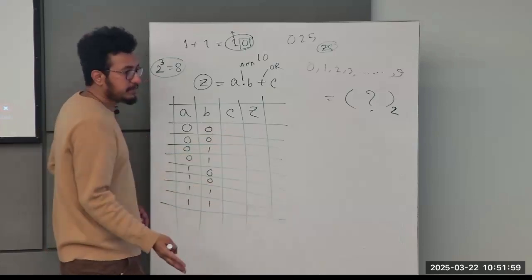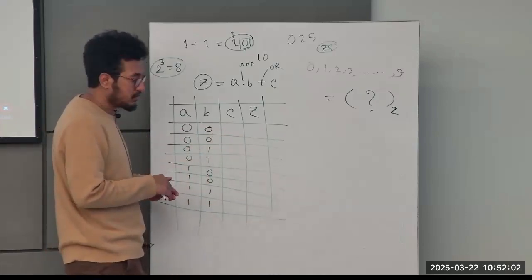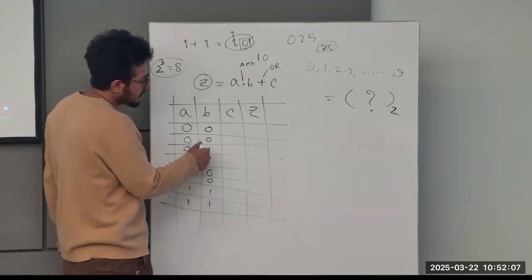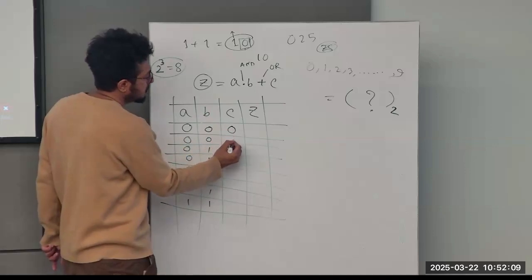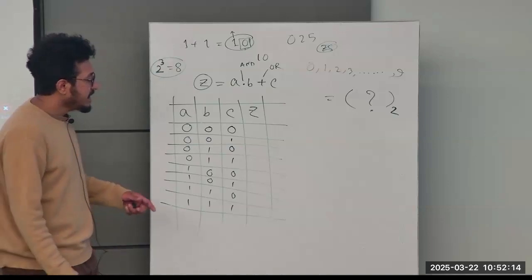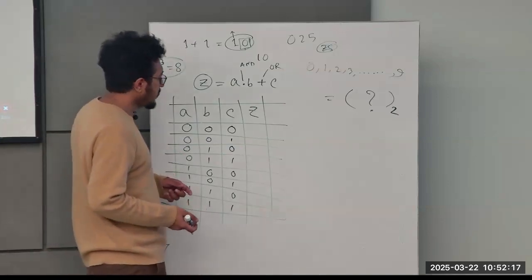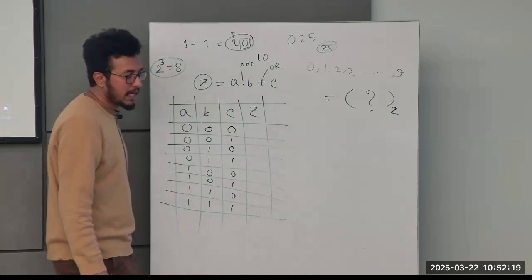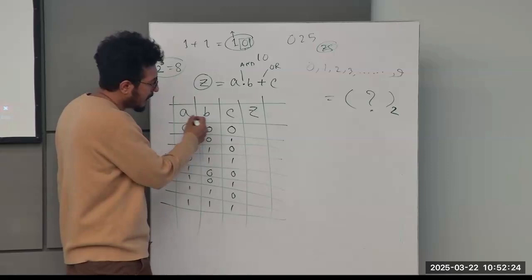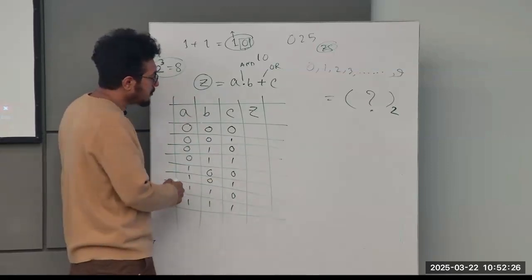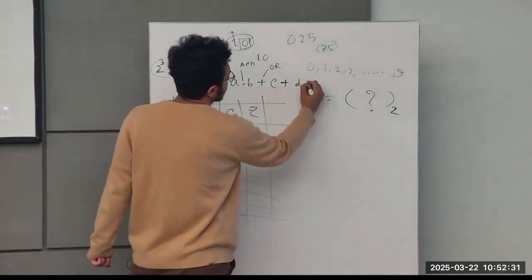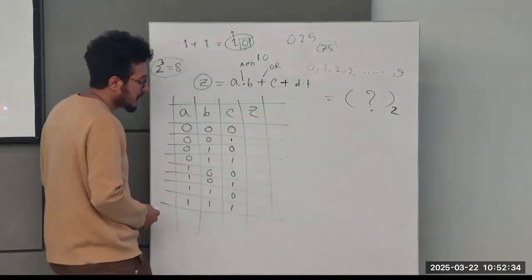Now for the last one, we divide by 2 again, so we have 2 2 2 2, right? Now we divide by 2 again. So 1. So 1 0 1 0 1 0 1 0. It is a very fast way to write your truth table. Otherwise you wonder, what combination have I written? What have I missed? Now you cannot miss. If I give you a truth table of 5 inputs, let's say I have another 5 inputs in my Boolean function,